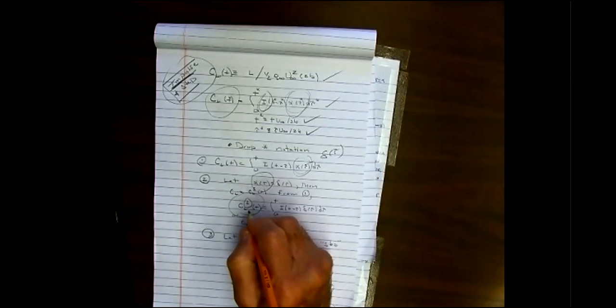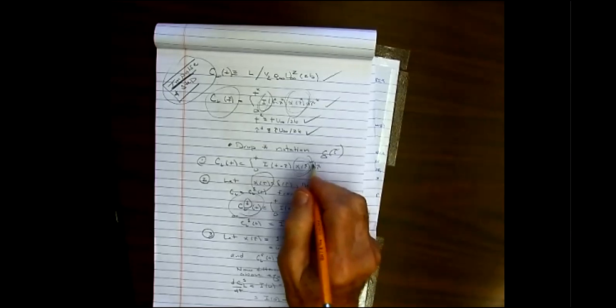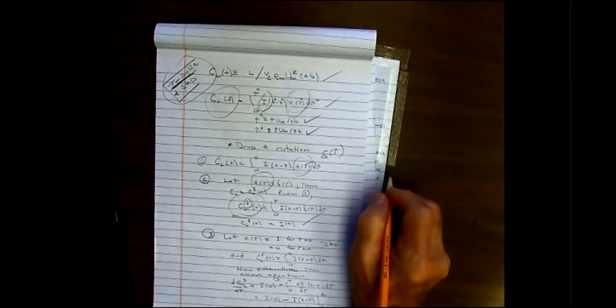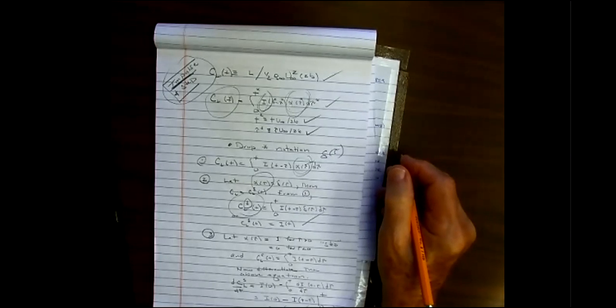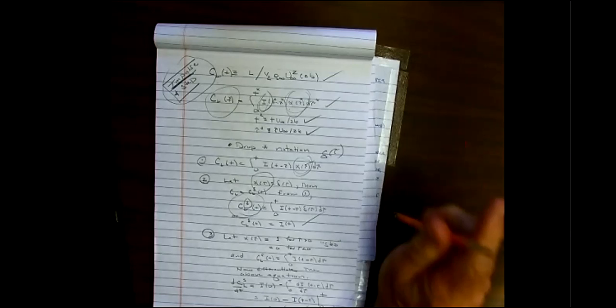This is a very special lift coefficient. It's the lift coefficient due to a delta function. Then if I can ever determine the lift coefficient due to a delta function, then I know what I of t is. It's the impulse function. The impulse function, as you see, is the lift coefficient due to an impulse or due to a delta function. So that's nice.